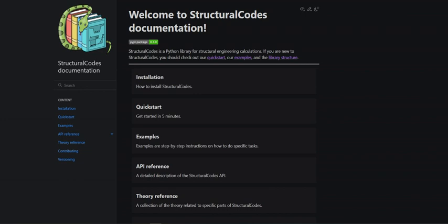Okay, this is quite heavily reinforced, or they're quite close to each other, so sure, perhaps not the best design, but. And would something like that, for Eurocode in particular, would you get some sort of an error code to say you've tried to place 4 bars in this relatively narrow section, the spacing is inadequate, or some sort of warning code like that? Yeah, that's a good question.